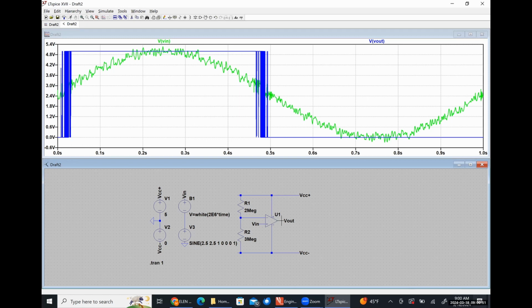Well, if our input voltage has noise, then it's going to cause the output to oscillate, because instead of having a smooth transition from below Vref to above Vref, it might go from below Vref to above Vref to back below to back above really quickly and all that kind of stuff. And so we see this ringing and oscillation, so our output signal isn't stable. So we are going to correct this by using positive feedback at the beginning of Wednesday's lecture.